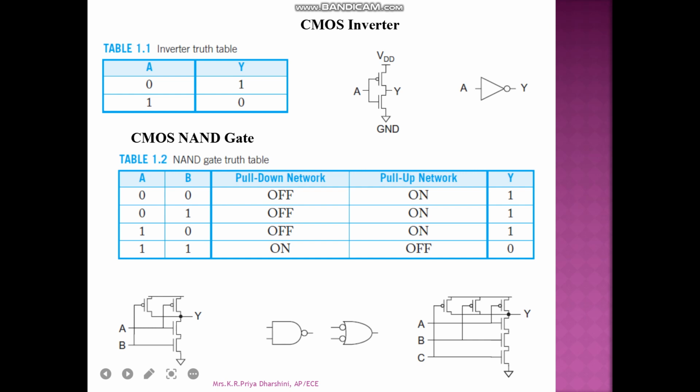So the CMOS inverter, combining both the PMOS and NMOS transistor, is called a CMOS inverter. So PMOS is connected to the VDD and NMOS is connected to the ground. In this, both are connected together to a single input A and both are connected together to a single output Y. So when an input is given, it will be inverted at the output part. So we can see the examples for the CMOS as the CMOS NAND gate and CMOS NOR gate.